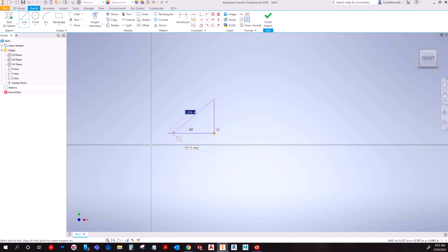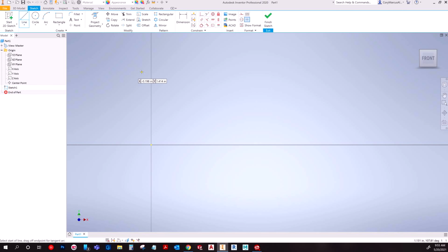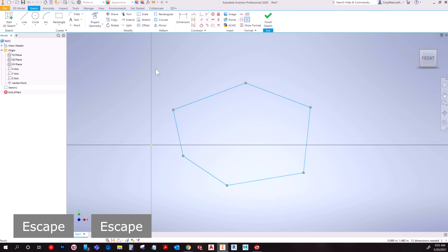Now, if I'm not careful and I end up drawing this just right, I can also end up putting a locked-in angle as well, like on that slant. So it's all about just knowing what to do. But to draw a line, you click the item. This applies for all of these pieces of sketch geometry, and there's some drop downs here with other options, but usually if it's important, it's probably on the main panel already. So I can click a line, and I can click a point, and then it has the continuation, and all you're doing is clicking a second point. You can then after that click another point, and so on. Nothing crazy. I can select it all and hit the delete key.